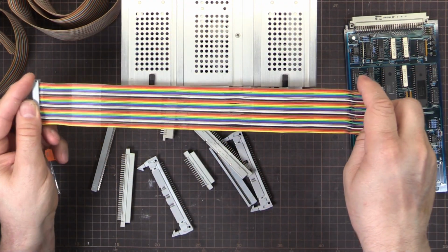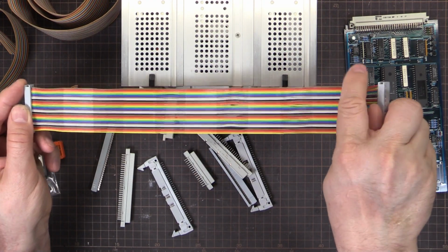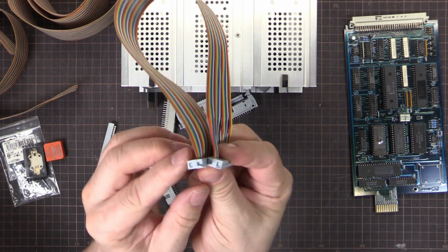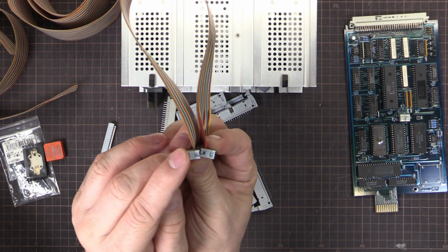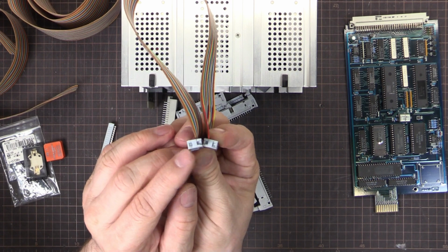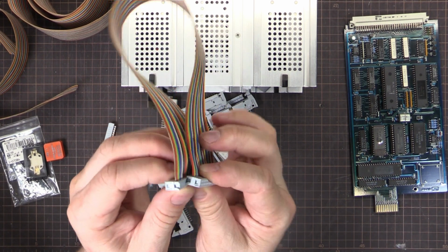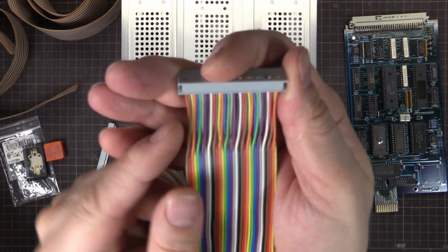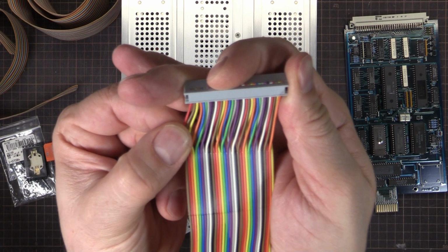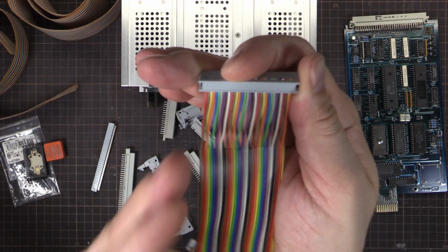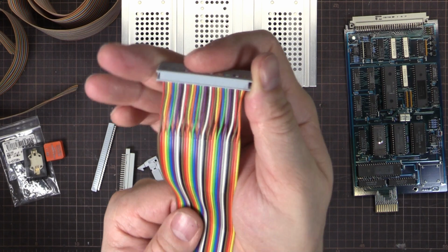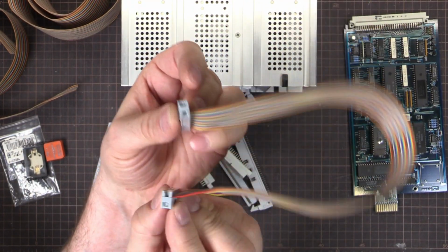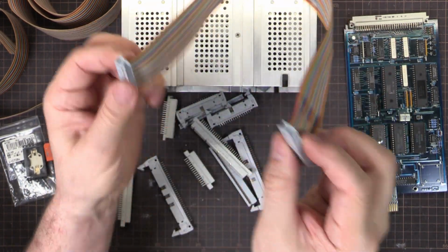But that's all right if you're going to plug it into a PCB, because you want pin 1 and pin 1 to be the same, but we don't. We want the pins to be reversed, so pin 1 goes to pin 2, and pin 2 goes to pin 1, and then the same, pin 3 to pin 4, and pin 4 to pin 3. So what I've had to do is flip each pair. I've split the cable, and then each pair gets rotated and rotated and rotated. It's a little bit tedious, but that's what I've had to do, and that makes it straight through like that, and that will work perfectly.